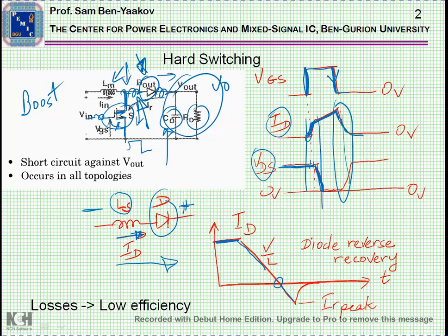This is called the reverse recovery of the diode. Now, the reason for the negative current, which may look strange at first, is that as long as you have charge carriers at the junction, the diode is conducting both ways. So until the charges are swept off the junction, the diode is conducting, and then eventually there'll be no charge in the junction and it'll snap back to zero.